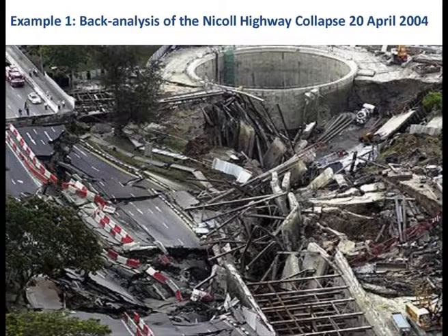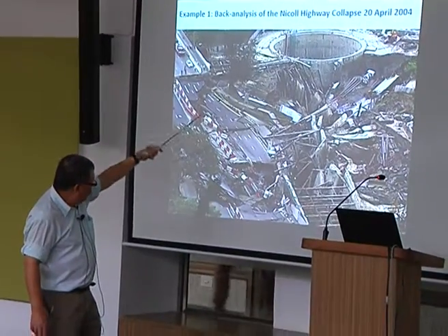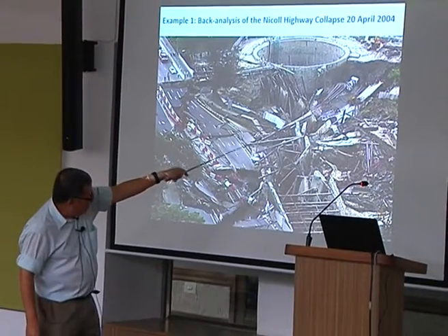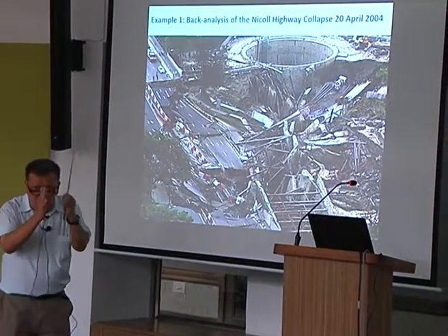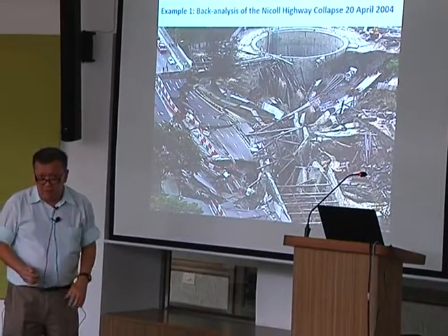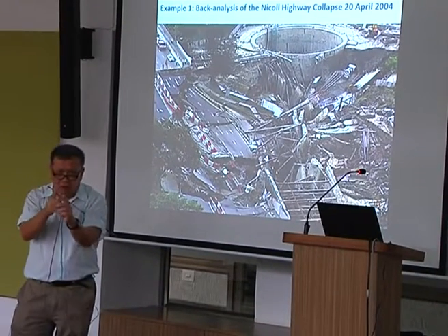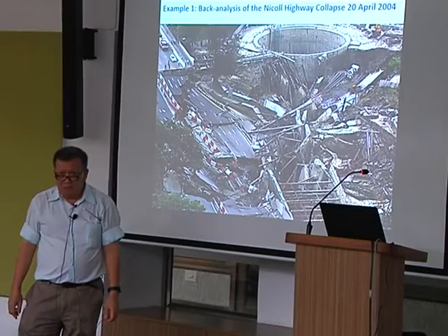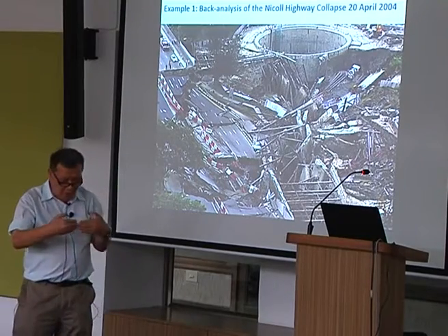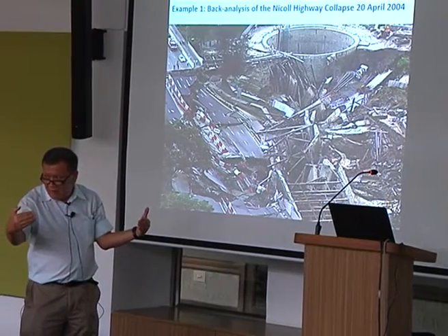This is the southern alignment. This is the south wall. That's the north wall coming down. You can see the south wall, the panel breakup. It's almost panel by panel breaking up, and the breaking up is occurring right at the joint between panels. There's no steel. And the wall line just comes out, it just goes splitting up.